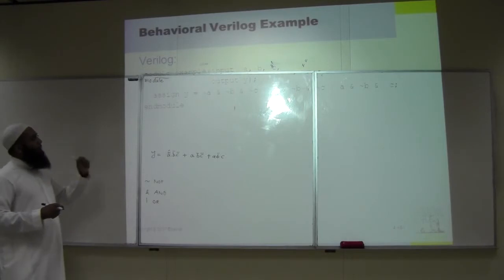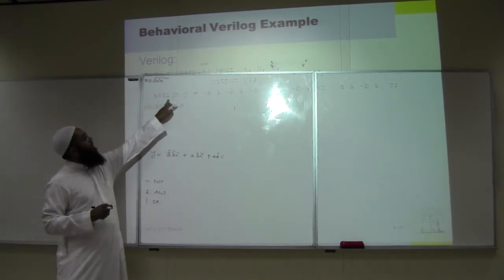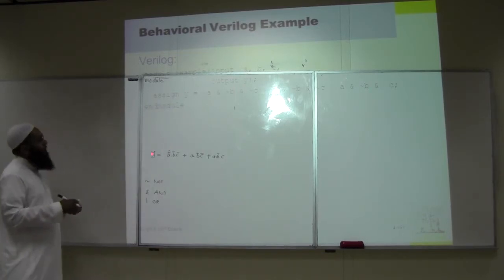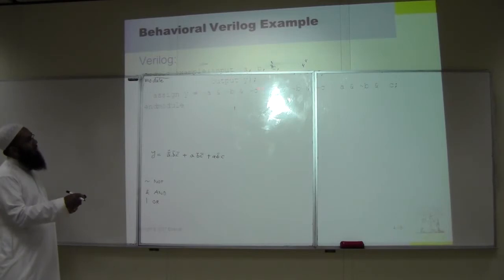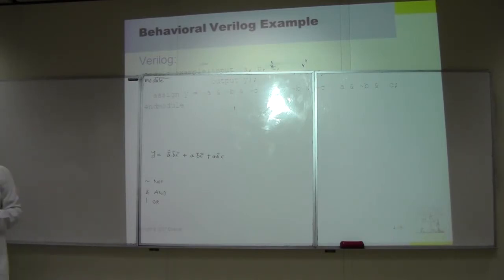But for Verilog you need to write one extra thing called assign. Assign means copy. So you write this one here, and at the beginning you write assign. Assign means evaluate and copy the value into Y. Okay? So this is how you write a module in Verilog.